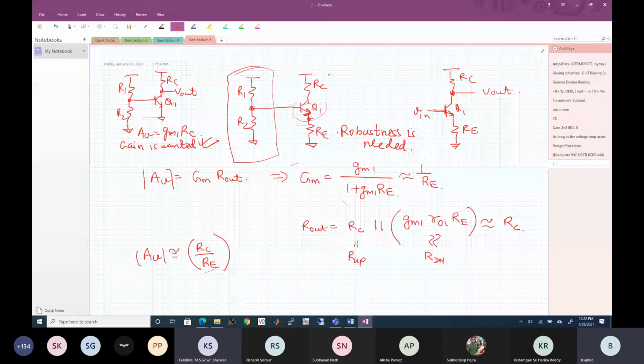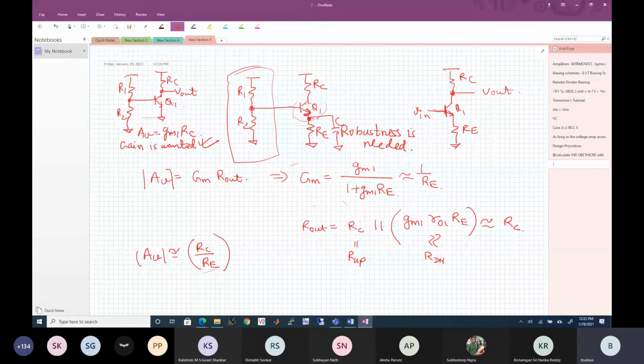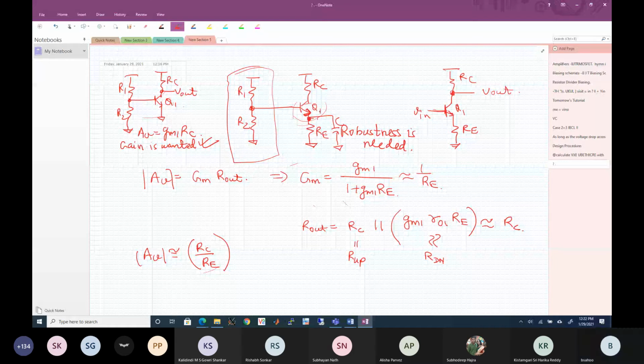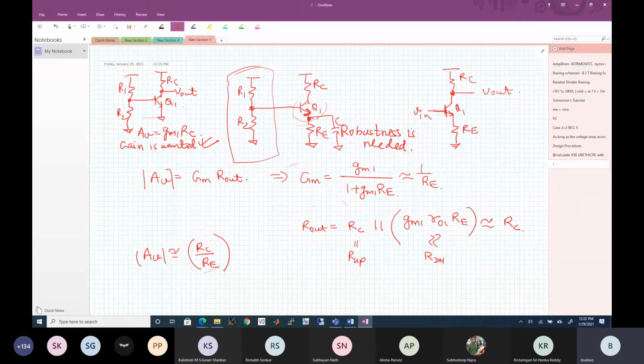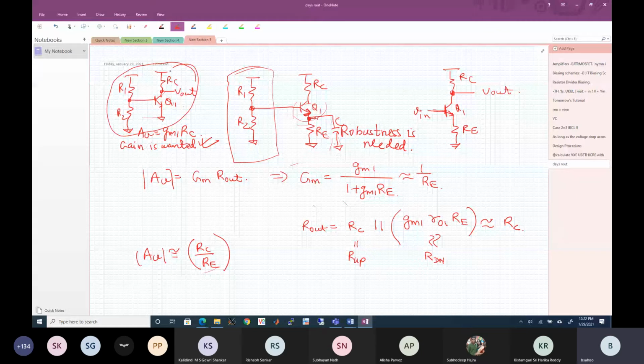Yeah, exactly. So that means you are going to put a capacitor over here. What does this do? It won't let any DC current through. It will set the bias point. So the robustness is due to the biasing. The biasing is undisturbed by this capacitor. But when I do the small signal, I want to amplify the signal. So I should not have this resistor. That means the signal should completely go to ground here. Any variation in the voltage here should be, this node should be an AC ground for all my practical signals of interest. So this is what we do and thereby get a huge amount of gain. We get the gain of this circuitry, but the robustness of this circuitry.